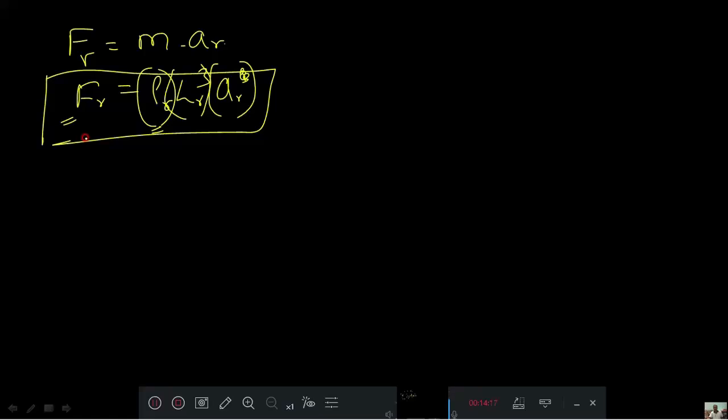By knowing some parameters, that is your Reynolds number or Froude number, and by using the law, you equate the Reynolds number for the prototype and the model, or the Froude number for the prototype and the model, and you will get some ratios. There you always assume the length ratio, and by knowing the length ratio you substitute and get the other parameters using basic equations. That's it.